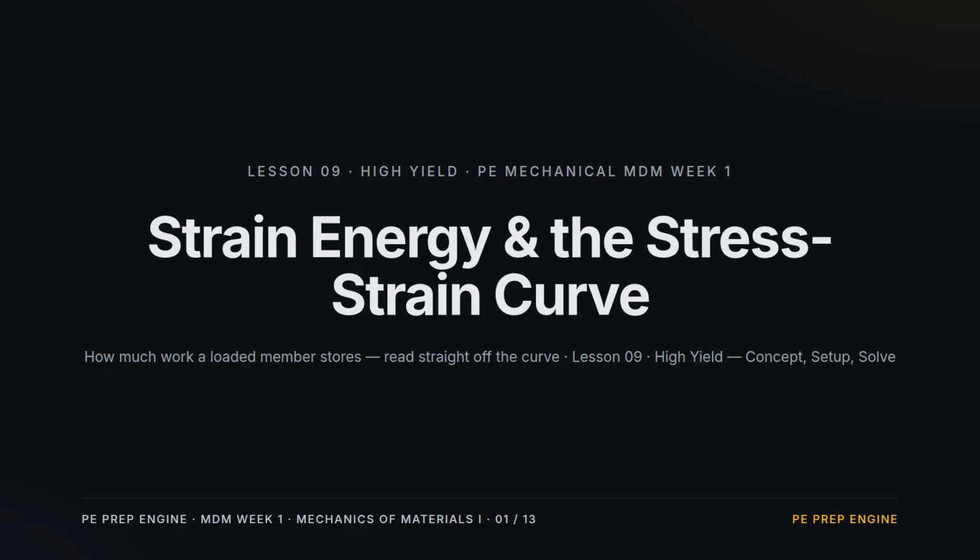Scale it per unit volume, and it becomes the area under the stress-strain curve, which also tells you two material properties the exam loves: resilience, the elastic energy to yield, and toughness, the total energy to fracture. One picture ties all of it together.